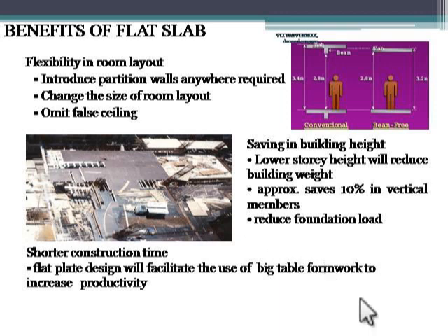Benefits of flat slab: flexible in room layout, partition walls wherever we require, change the size of rooms, omit false ceiling, saving in building height. Lower storey height will reduce building weight, improve the cost by nearly 10%, and reduce foundation load. In shorter construction time, we can do the slab within a shorter time. Flat slab design will facilitate the use of big table formwork to increase productivity.